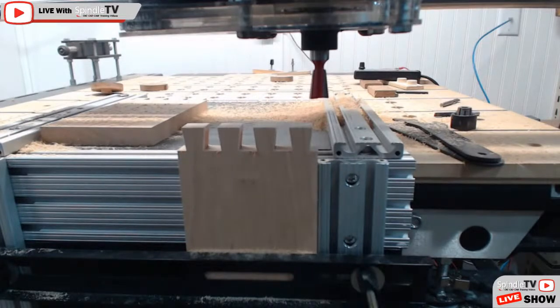Now that you have the bottom fence adjusted for the right height for your piece, all you should have to do is flip it to the other side and rotate and clamp it. Exactly. Yeah, I'm going to do the pin board just so you guys can see that cut and everything. But yes, all I would do is just flip the board over, clamp, cut. And I would normally, while I have the end mill in, do all the end mill cuts.